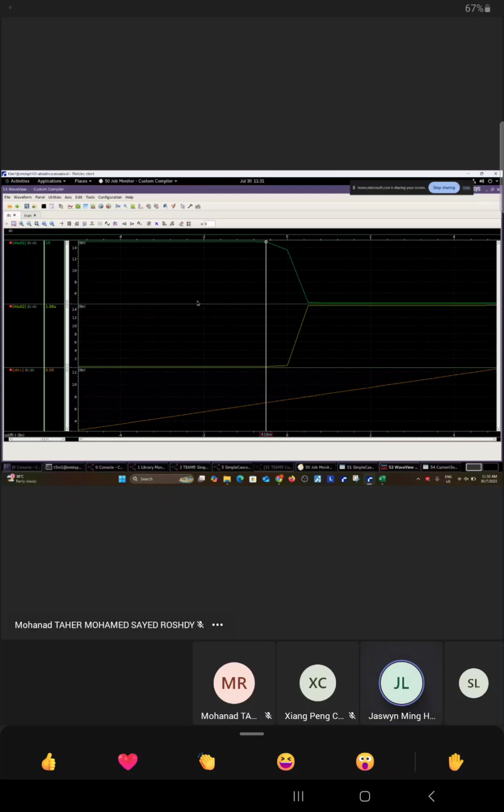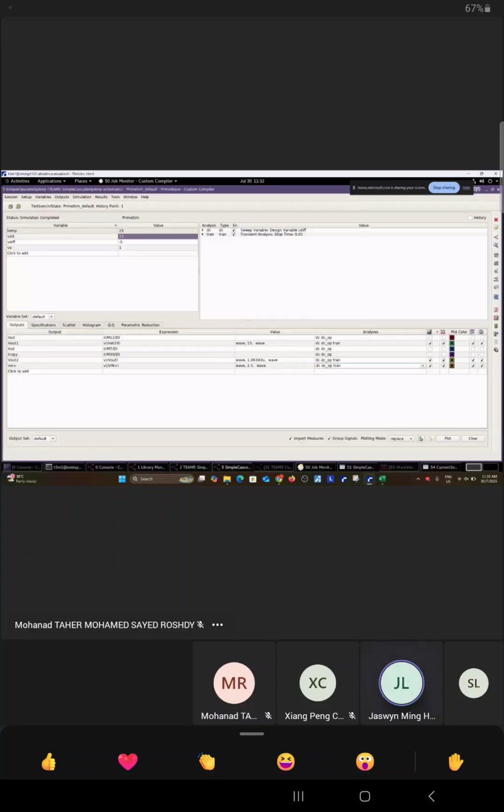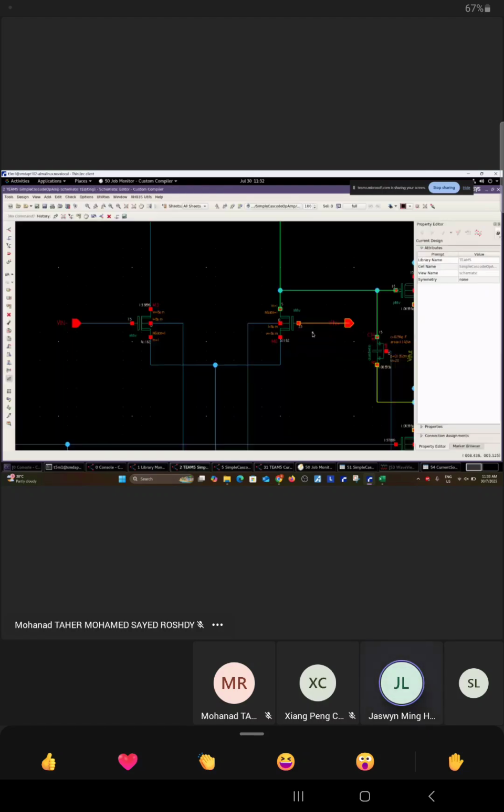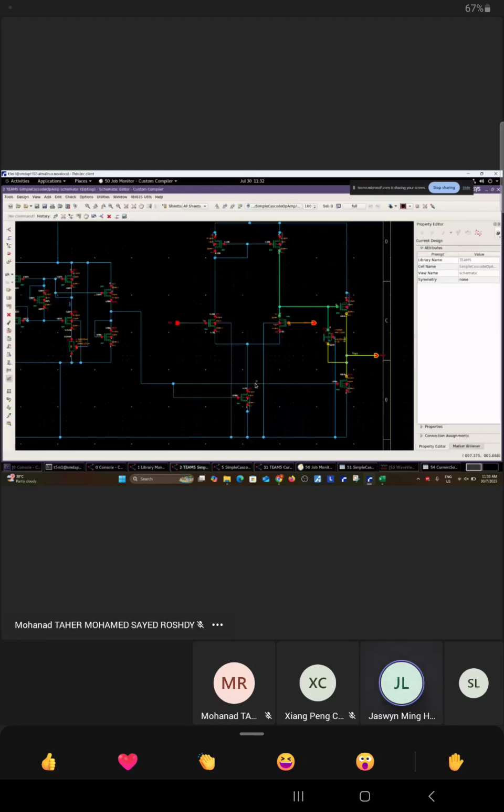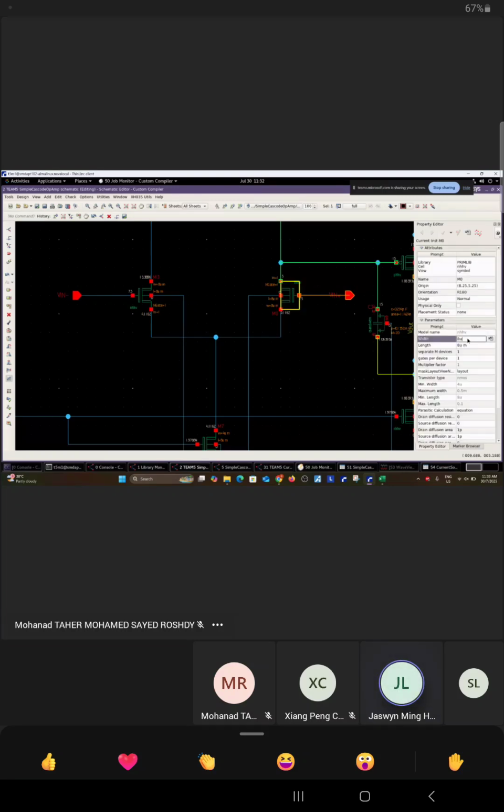Just now, okay, I lost track already. Just now when we increased the gain to be very high, did it actually help to make the graph steeper near the region? Let's put it back to 200. Yeah, go back. Since we know decreasing doesn't help in any way, and they want higher drive current, change this back to a high value. Okay, let's make it 40 again. Then your tail current, I think, can increase back.